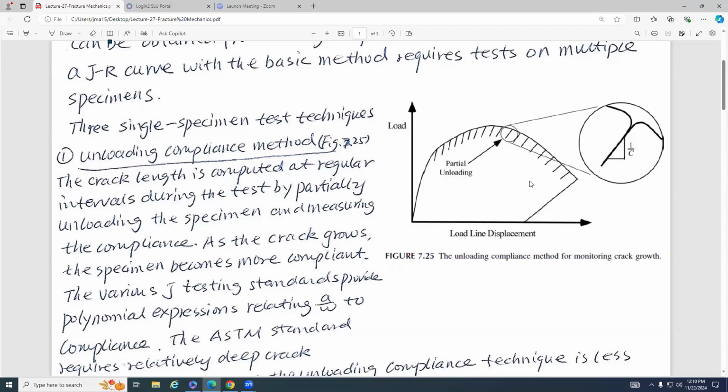At some point, the material used, and then we have strain hardening, and then at some time, after we get here, we just remove the load. This is partially unloading. If we totally remove the load, it will come to the x-axis. You should know that, okay? So this one goes here, so that is partially unloading. Fully unloading means that this straight line will go all the way down to intersect with the x-axis. You understand?